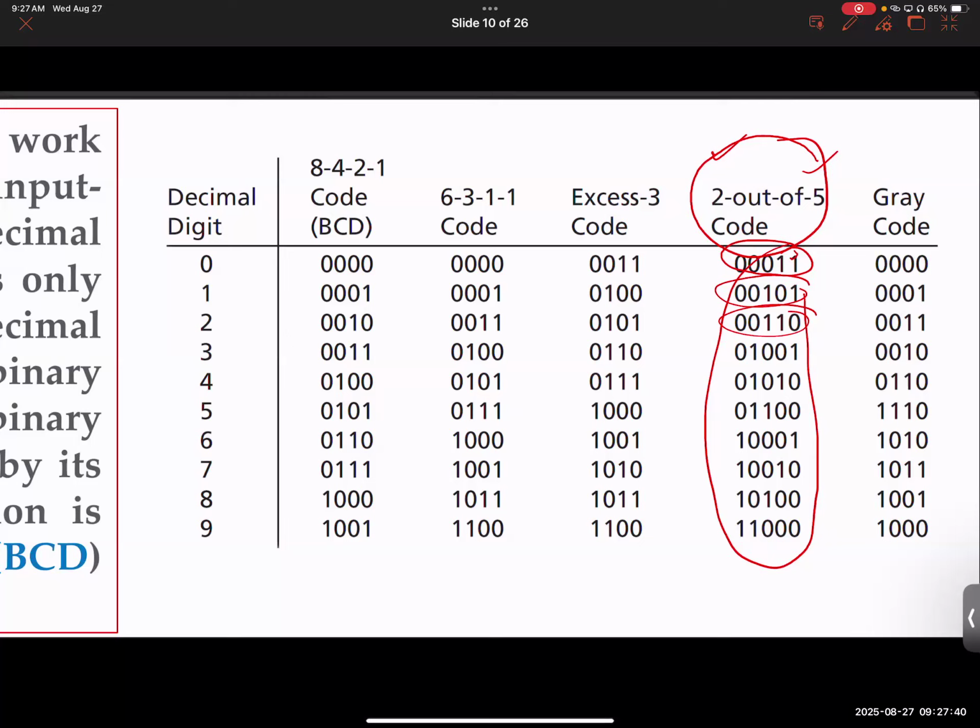So there is an asymmetry, more zeros than 1s. 2 1s, 3 0s. And depending on the position of these ones, you could represent 0, 1, 2, 3, 5, whatever. So these are unique, obviously. For example, this is a unique code for 4, but this is not a direct conversion of 4 to binary, is it? It is not. It is just a code that people came up with using 2 ones and 3 zeros. So apparently you need 5 digits to achieve that.